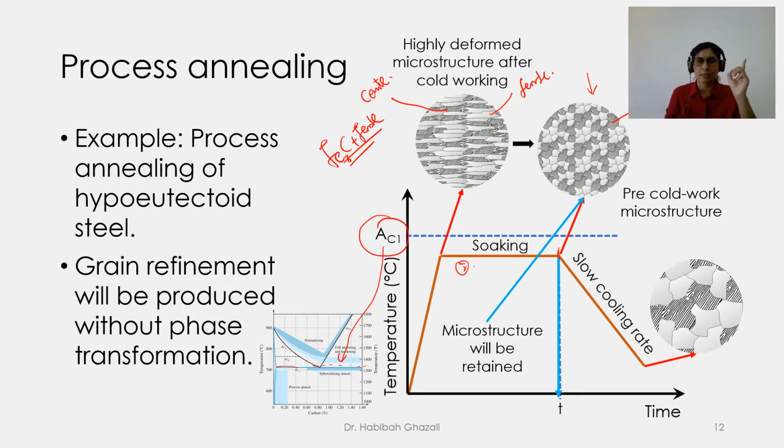So during the first slide where I showed you the clip, that's what they did. They wanted to retain that microstructure, which will give a higher strength. What they did is that they took it out and put it inside the water straight away. So the temperature will drop to room temperature at a rapid cooling rate.